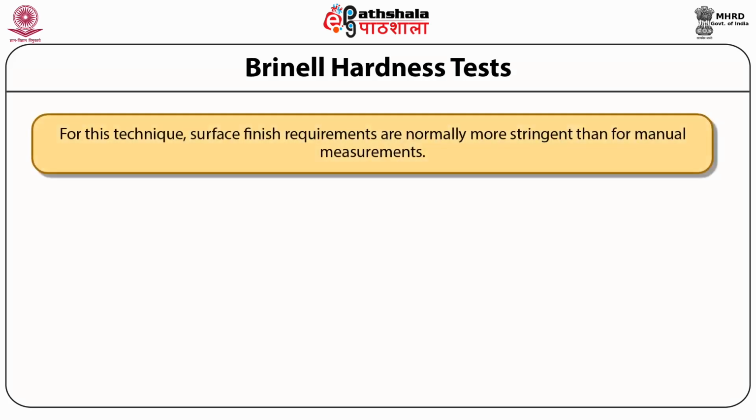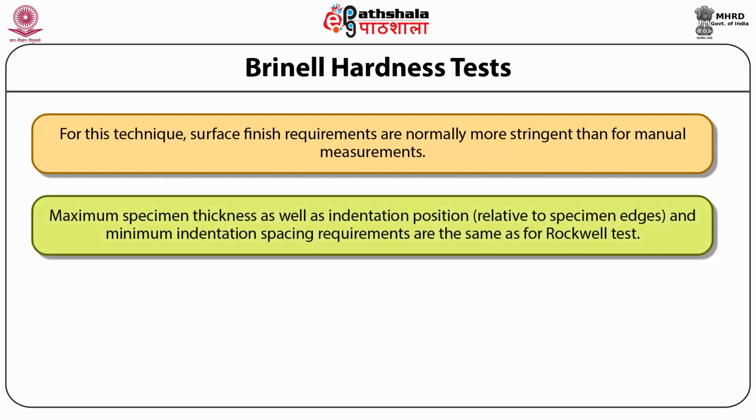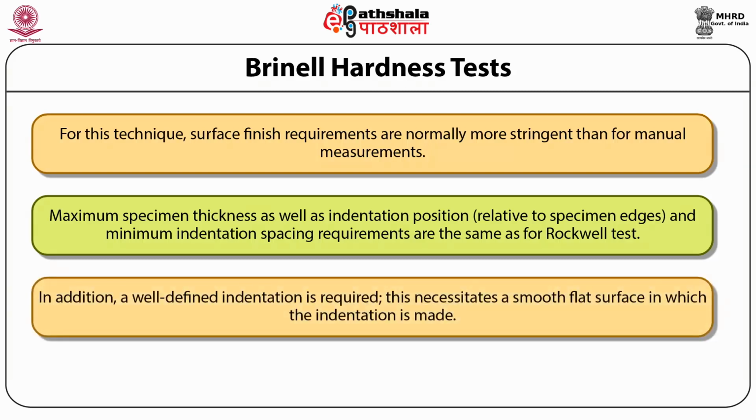For this technique, surface finish requirements are normally more stringent than for manual measurements. Maximum specimen thickness as well as indentation position relative to specimen edges and minimum indentation spacing requirements are the same as for Rockwell tests. In addition, a well-defined indentation is required. This necessitates a smooth, flat surface in which the indentation is made.